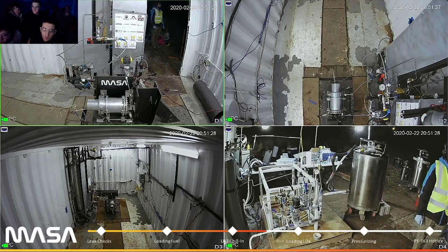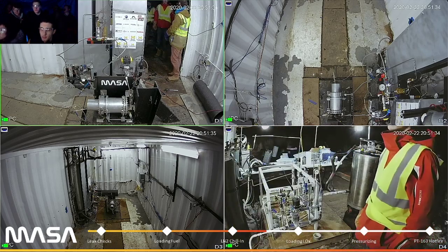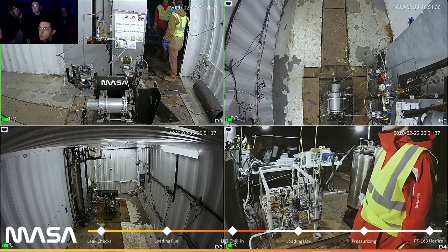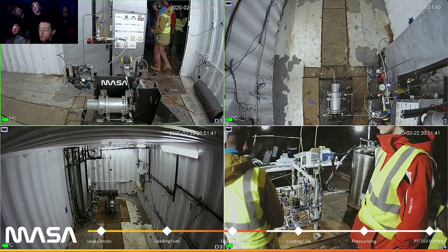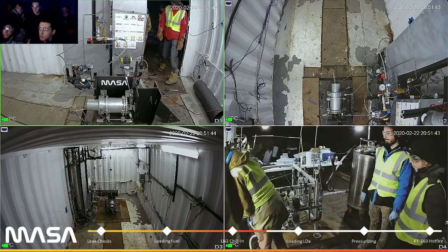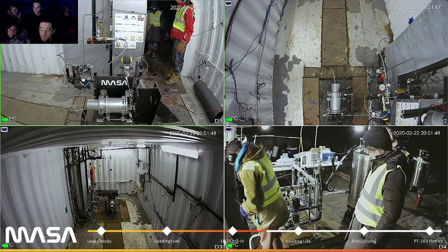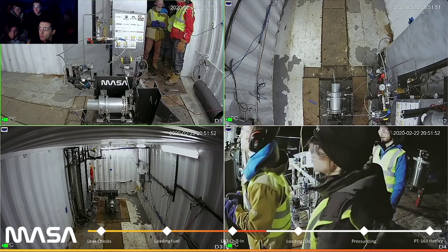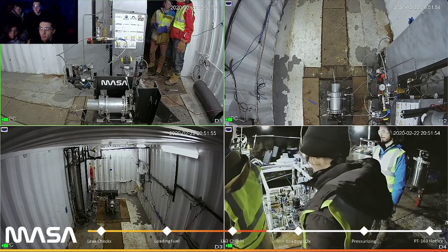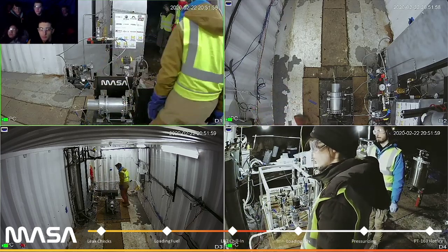Sorry, to finish my last point, we run a regen circuit, so fuel takes longer to flow. There's a longer flow path. That being said, the valve timings are also different. From some of our cold flow data, we have figured out, at least right now, the best way to stagger our valves so both propellants enter the chamber at exactly the same point in time. That being said, we are opting to lead with fuel and also end with fuel. So at the beginning and the end of the burn, you run slightly fuel rich, just to help keep some of the temperatures down in the engine and prevent the metal inside oxidizing.